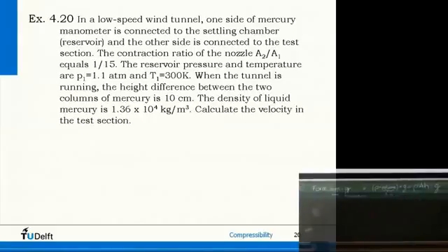So we still have an A in here for the force, right? Now, the thing is at rest, so if we look at the height of this one, we have an equal force pushing here as pushing here. So the forces on the left side are P1 A, balance of forces. On the right side we have P2 A pushing plus the force of this column, so plus rho g h times A. Now you see indeed we have A everywhere. The area of the tube, the area of the manometer, is not so interesting, so it drops out.